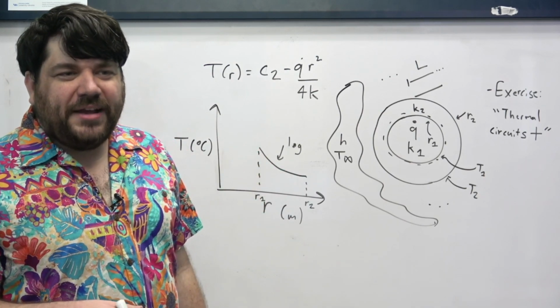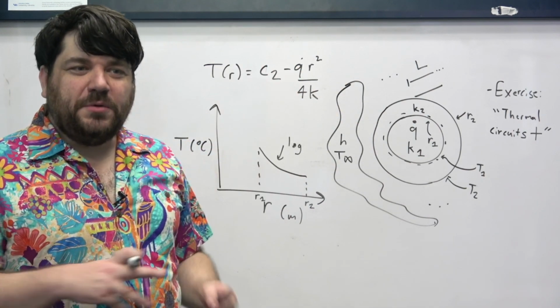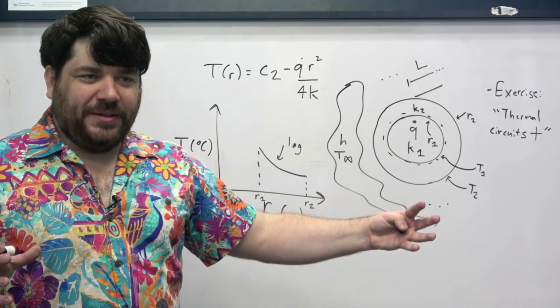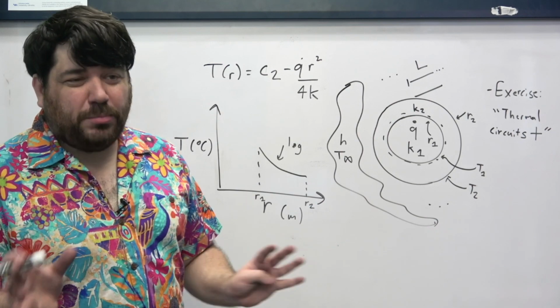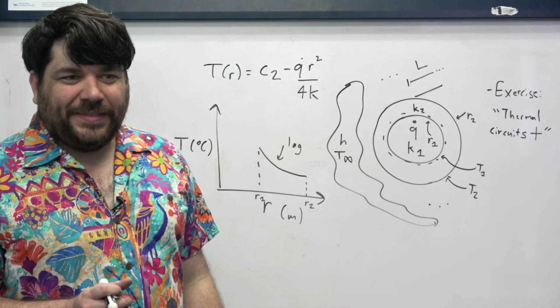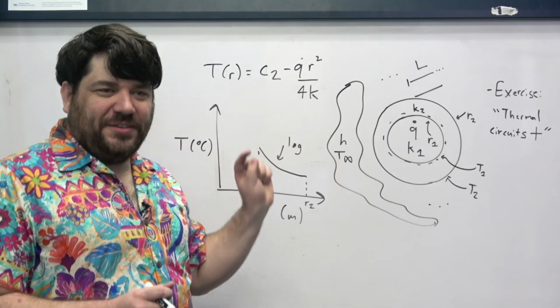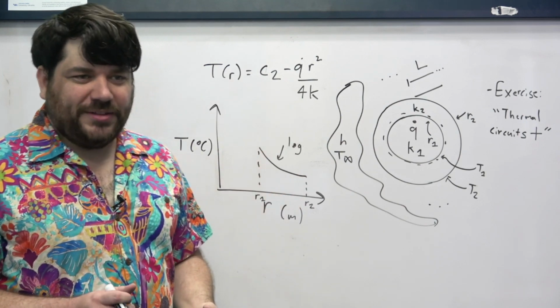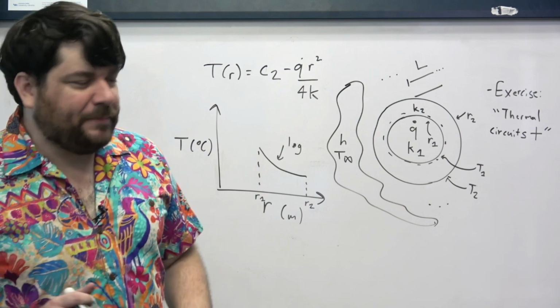But also you can imagine that as the cylinder becomes larger and larger, you expect the temperature distribution to eventually at least approximately smooth out. If this thing curves down this way, that just means that the temperature decreases steeper and steeper, right? What you want is for the temperature decrease to be gentler and gentler as R increases. So that's a way to think about it.